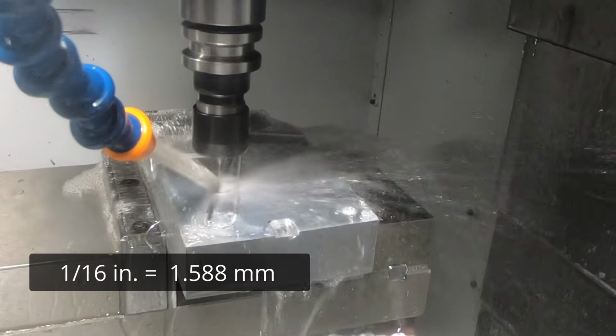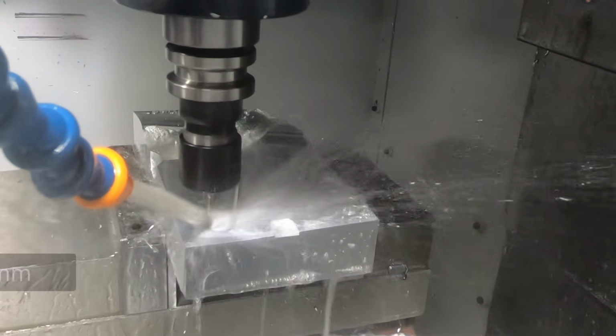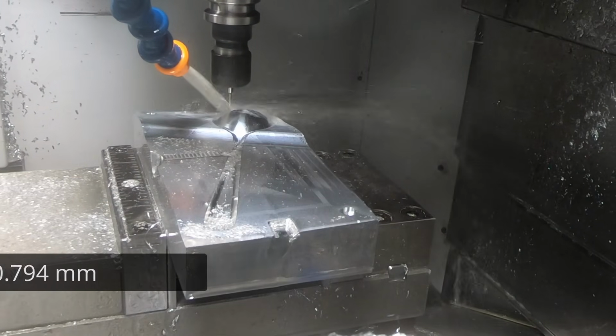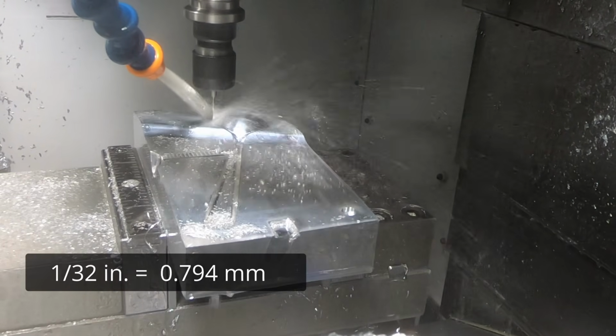Then a 1/16 inch diameter end mill to start cleaning up the fillet at the edges of the spoon. And finally a 1/32 inch diameter ball end mill to finish cleaning up the fillets at the edges of the spoon.